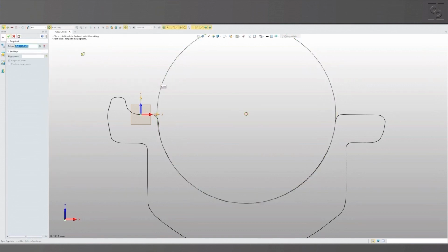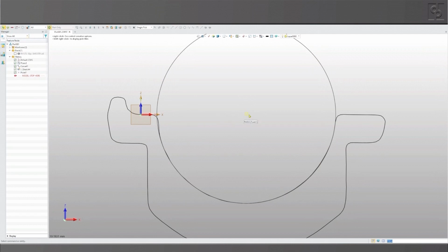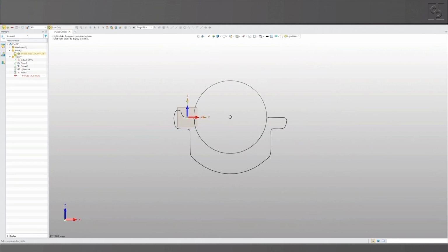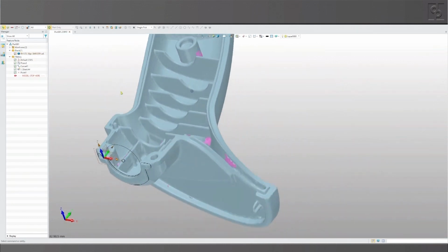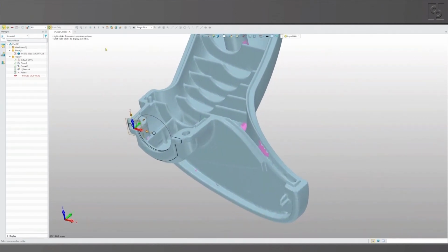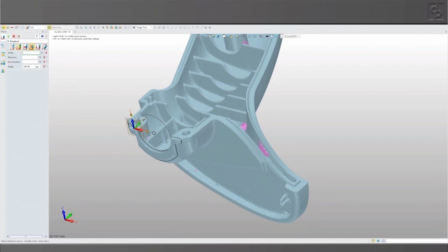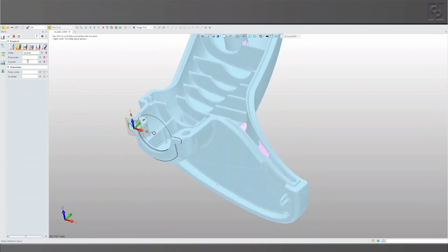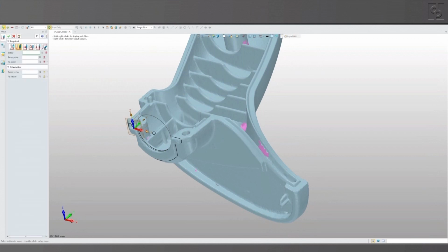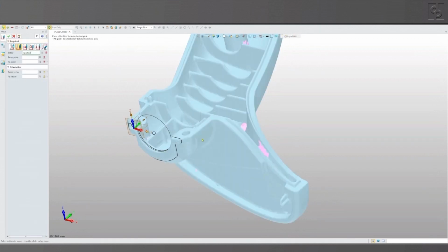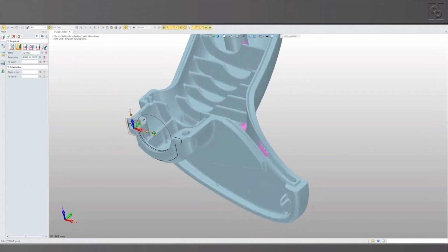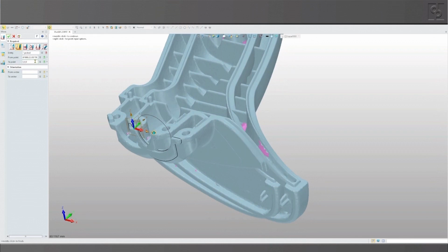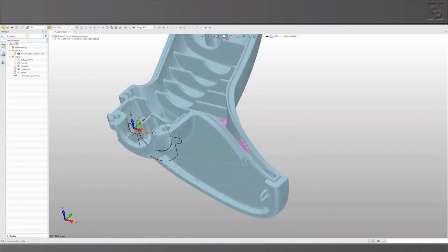So positioning that circle there, what I see is that the cross section through the scan is weaving in and out of the sketched circle, which is a good sign. It means that I'm not too big and not too small, but I'm just about average. And I put a point at the center, which is where I want to move the scan from to align it with the absolute zero on the construction axis. So a simple point-to-point move of the scan and delete the construction entities.